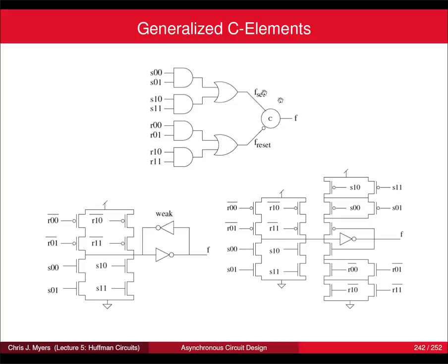So you can implement this logic gate here, shown as complex and as basic logic gates, in CMOS like so. You have your set functions implemented in NMOS transistors. If I want to implement that AND gate, when that switch is on and that switch is on, I'm going to have ground coming up through here. That gets inverted to become a 1, and so this turns on. Or if this AND gate is on, this pair of transistors is on, that will also set the function to 1.